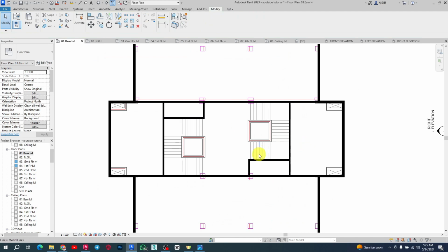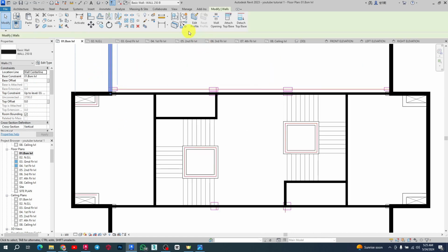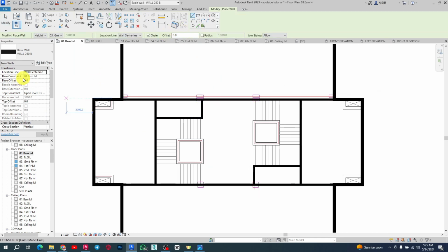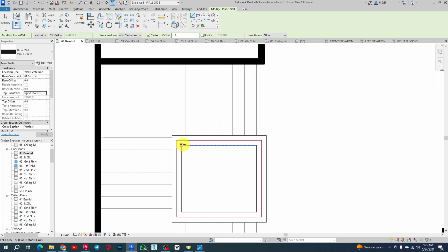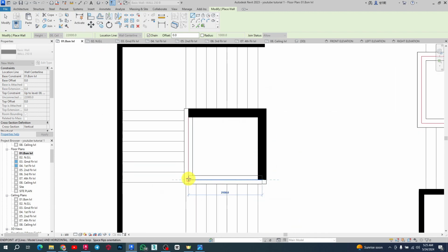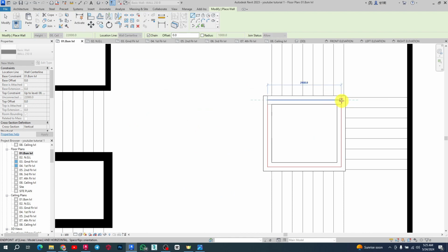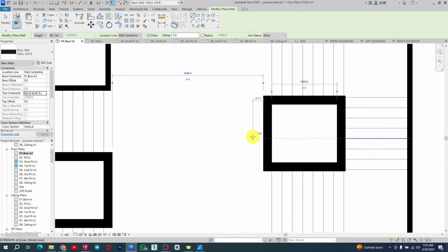So that is it. Let me just model my shaft wall to the shaft here. So I'm going to use this 250, right? So just click on one of the walls, click create similar, and I want it to start from the basement now and end at the ceiling level. I just want all of it to go, the shaft to go at once, right? So I'm just going to draw this one right now, draw this, and add my shaft position there. So have this one here, so that I don't have to always model this at a different level, right?